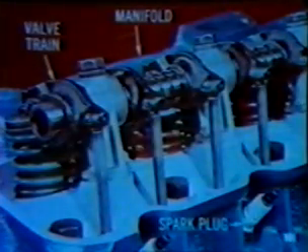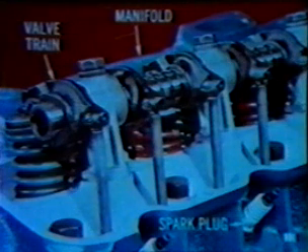The last part of the compression system is the cylinder head. It also is a supporting part of the engine and is built sturdily of cast iron. In addition to forming the top of the combustion chambers, the cylinder head provides mountings for the intake and exhaust manifolds, spark plugs, engine valves, and other components of the valve train. Oil and water passages also are part of the cylinder head.